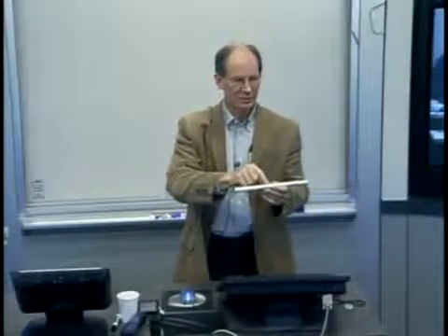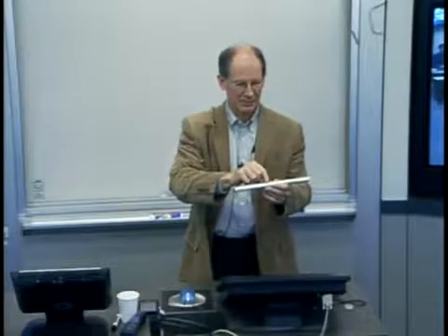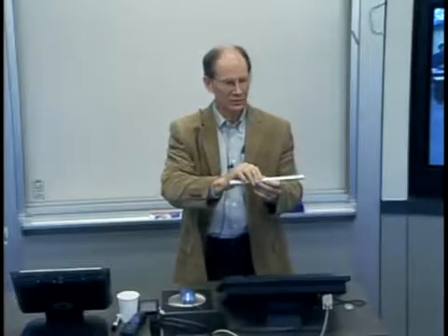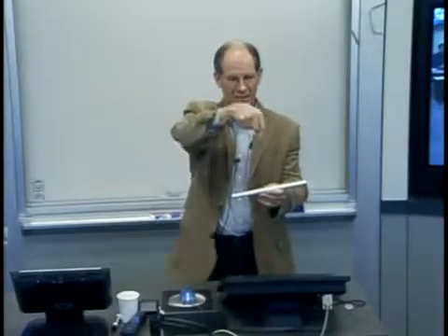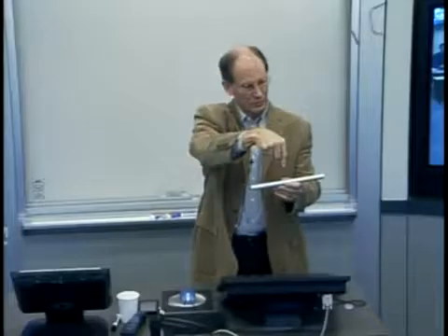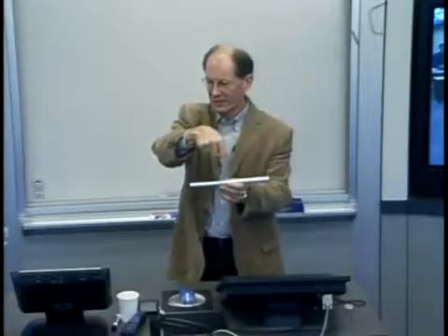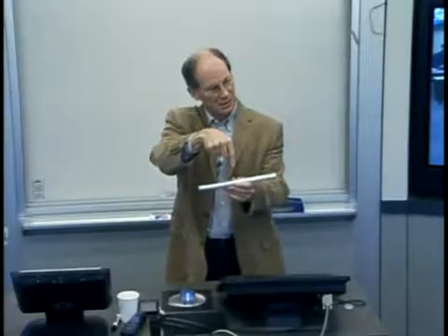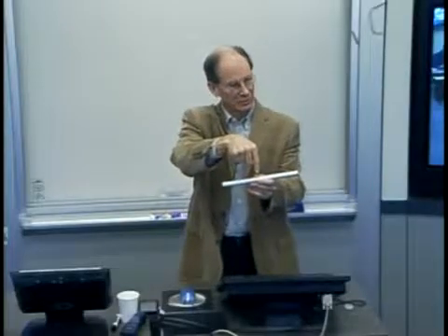Yeah, if I had a point source, a laser or an arc or something like that, a laser's a better example, and I needed to do something right here, maybe thermally deform this or join it or something like that, then the key would be both the value of that energy and where I put it. So location would be really important.